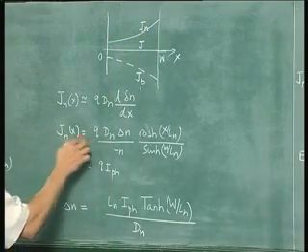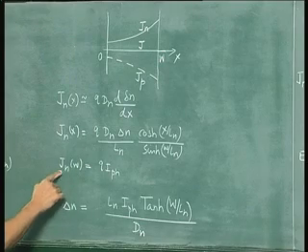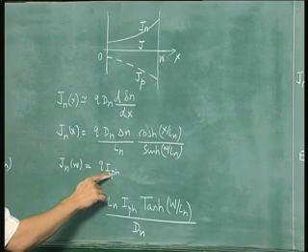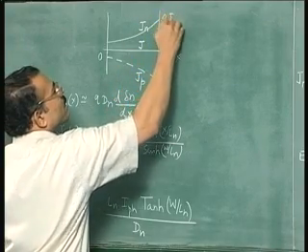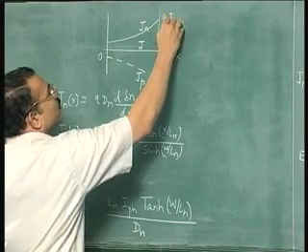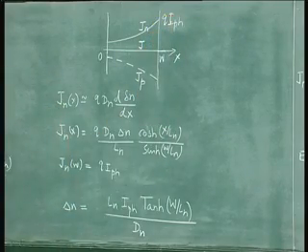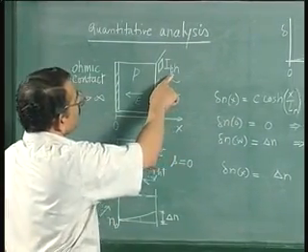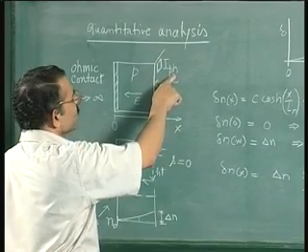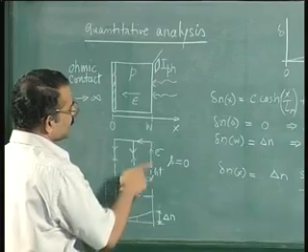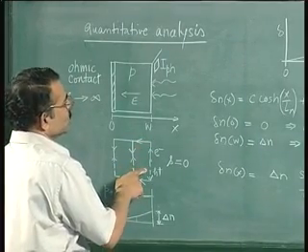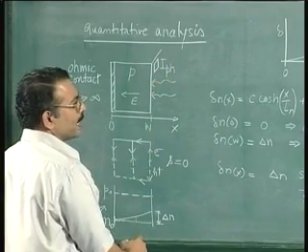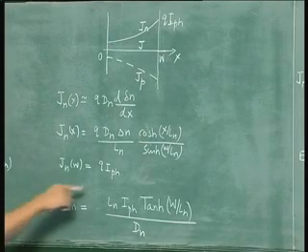Now the boundary value of Jn at x equal to W, Jn at W, that is Jn here, is q times I ph, that is the intensity of illumination. This is given in the problem. How? Let us look at this particular situation. The intensity of photons is I ph and each photon is giving rise to an electron hole pair. So this is how the current density results. So q times the photon intensity is simply the magnitude of the current density of electrons at that end. So that is how you get this.